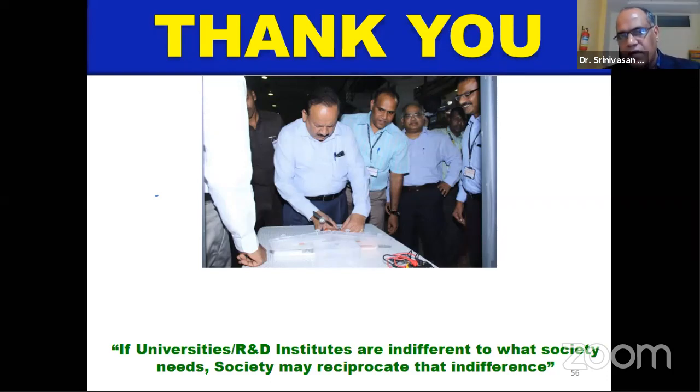Now what Tesla is doing is tying up with a China-based company for developing a cost-effective battery. They have the complete battery fabrication process know-how. Now they are working on whatever the existing battery chemistry is. They are using nickel manganese cobalt oxide as a cathode, or nickel cobalt aluminum oxide as a cathode, and graphite as an anode, which has higher energy density, and then you will end up with a high driving range. But if you want to reduce the cost, you have to look for alternative materials.